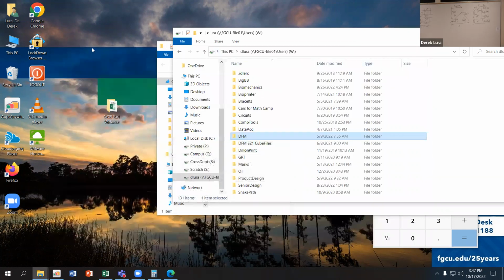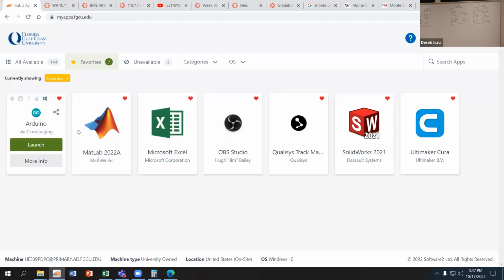The next thing I want to show you is that these are not necessarily accurate. This is a tolerance stack up from a tolerance standpoint, because we're treating all of our output as a linear combination of our inputs. And if we're looking at the actual variance of a part, it's usually not going to be a square distribution. It's going to be some kind of normal distribution. And so if we want to get a better understanding of how that works mathematically, it's good to simulate that in something like MATLAB. So get on Apps Anywhere if you're not already on there.